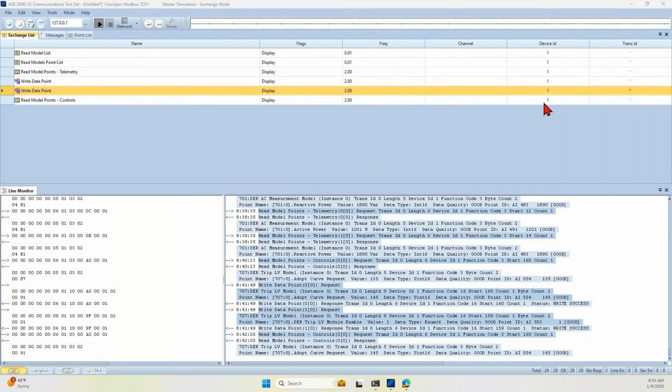For example, on RS485, if you keep on polling the devices, and if there are too many devices, you won't be able to poll at a faster rate. So you'll have to look at the practical scenarios and deploy the devices accordingly.